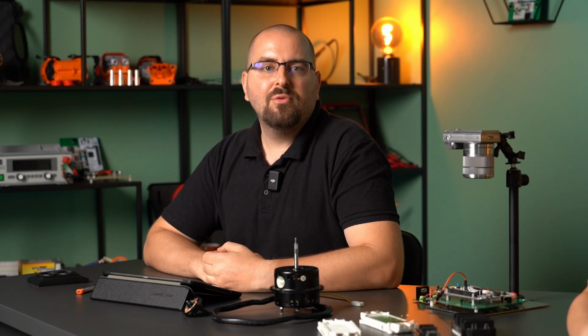These types of motors were needed for several reasons. A major disadvantage of brushed DC motors is that an electrical arc, more commonly known as an electrical spark, is generated between the carbon brush and the commutator when the connection is broken. This rules out their use in mines and other places where this spark could cause a fire. In addition, carbon brushes wear during use, and because of the fine dust they generate, they cannot be used in places where high cleanliness is required.